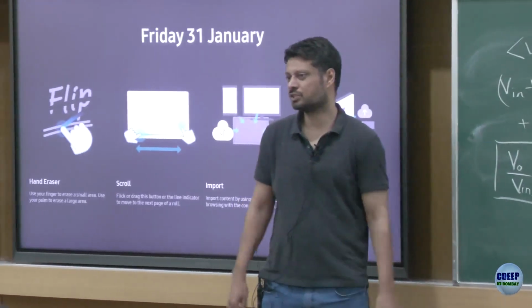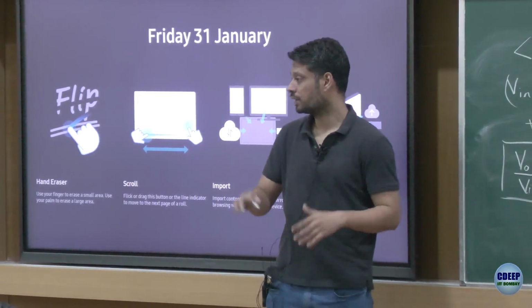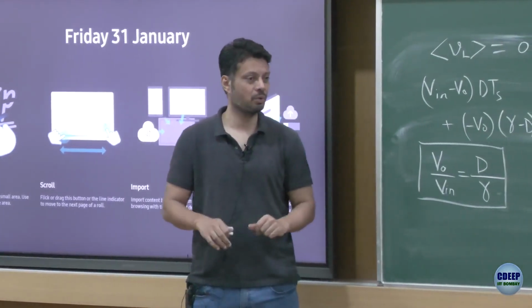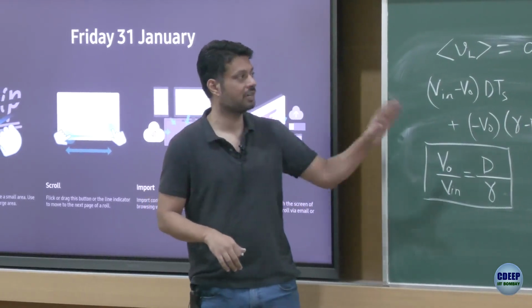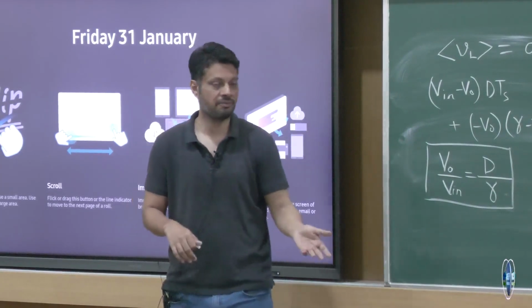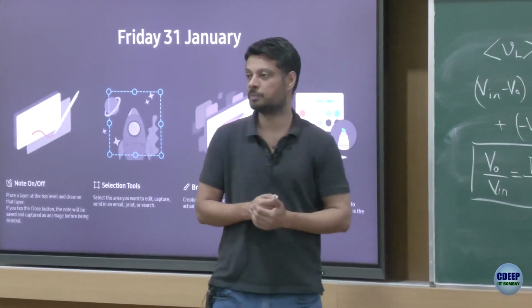Of course, this is not an advanced course, so we won't really go into details of how you do the closed loop control of this system and how you model it in more detail. Those things we don't do, but you get a flavor that you cannot just keep a fixed duty cycle and have this work. In any application you pick, there would be a closed loop system to control these power electronic converters.